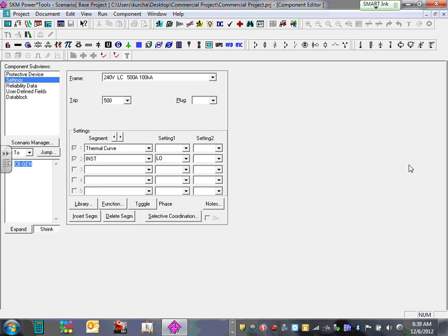Here's the instantaneous. This is one of the dumbest circuit breakers you can buy. It only adjusts the instantaneous and the thermal. It's not electronic. We can adjust everything. Next project, we're going to be using very adaptable, very adjustable electronic circuit breakers. For this project, because the project amp is small, it's not worth it to buy electronic circuit breakers for these. So that's what we're using.